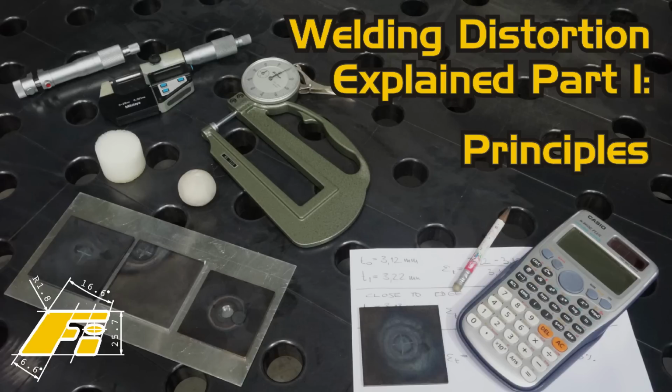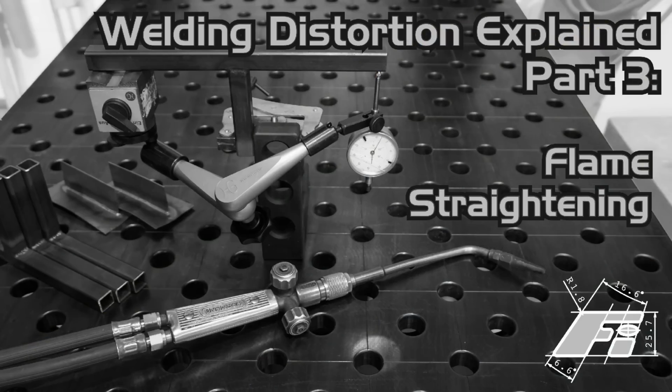The primary mechanism of welding distortion takes place while the material is solid, during local heating or cooling. Consequently, we can study the primary mechanism without local melting. In other words, there is no need to weld in order to study distortion as we encounter with welding. This is, for example, the case during flame straightening, where we turn the tables. Here we smartly apply local heat to create on-purpose distortion in order to counteract welding distortion.